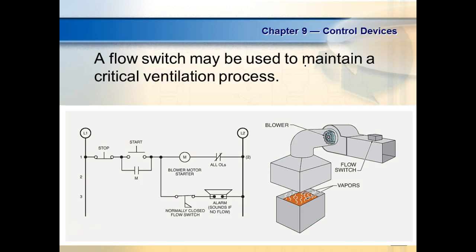So how would this circuit right here work, guys? Oh, they missed line 2. Line 2 should be right here because it's supposed to line up with the line, right? So what would this do? Push start button, should seal itself in, right?